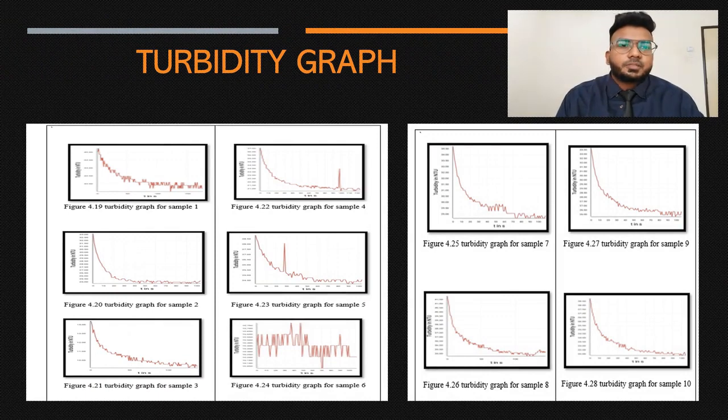Turbidity can be referred to as the amount of cloudiness of water. According to Malaysia's National Water Quality Standard, turbidity values of 50 NTU are classified as Class 2A and Class 2B. Class 2A is primarily concerned with conventional water supply or water treatment, and fishery is concerned with the delicate species. Class 2B is for recreational body contact.